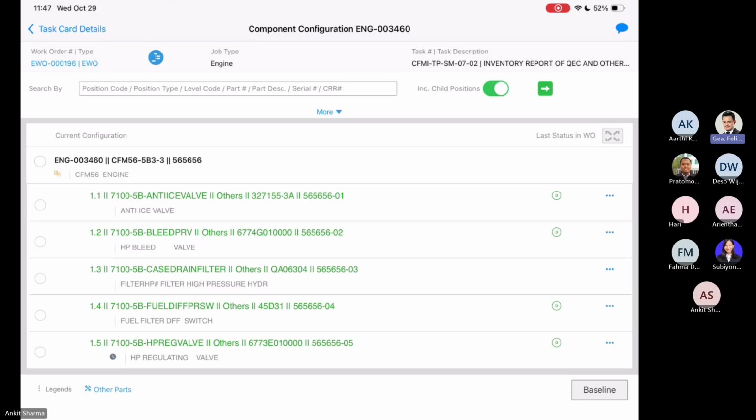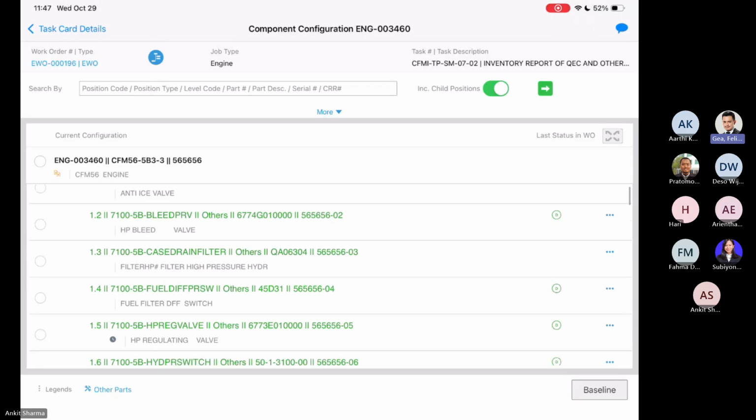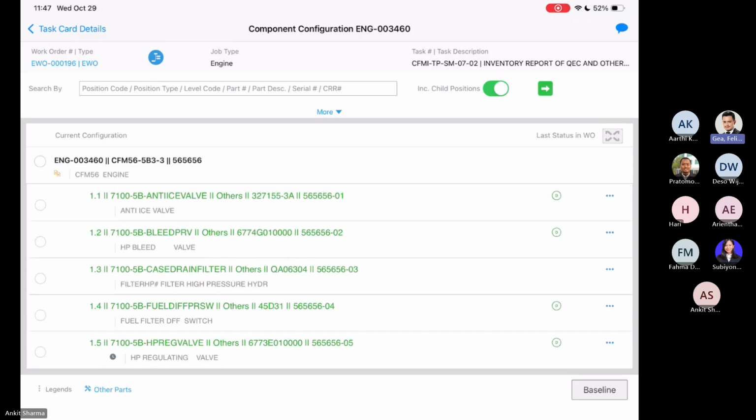The primary input for this would be the visit reference. We had updated the installed part and serial number as we had received from the customer in the document. This is the reference from the first stage, the pre-induction stage, so you have the part and serial numbers that were identified at that point listed out here. From here, for each and every module that you identify on the physical engine, if the configuration looks right, you proceed with your disassembly process.